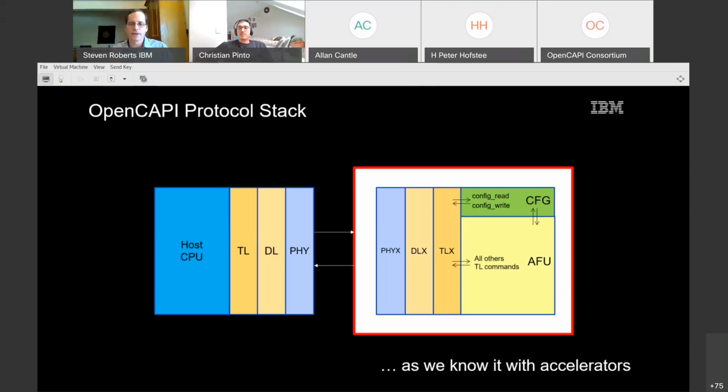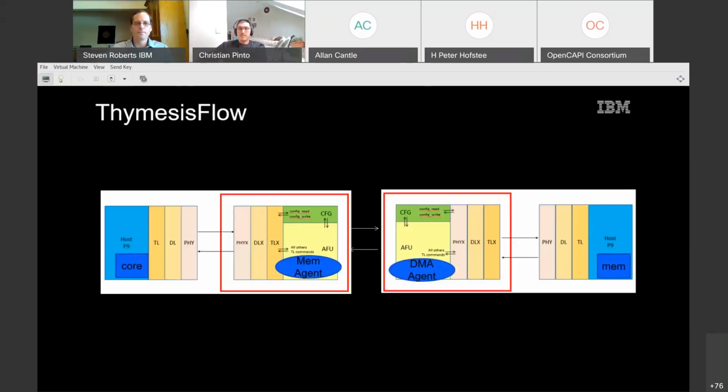And the system on the right is an FPGA. Typically, the area in the red rectangle is implemented as an FPGA or even an ASIC accelerator. And this is the accelerator model, as we know it, where these two regions are able to coherently share data back and forth. When we progress beyond that model with the MI flow, you integrate these AFU connections between two hosts. So the FPGAs have hard IP, SerDes type of interfaces that can connect each other together.